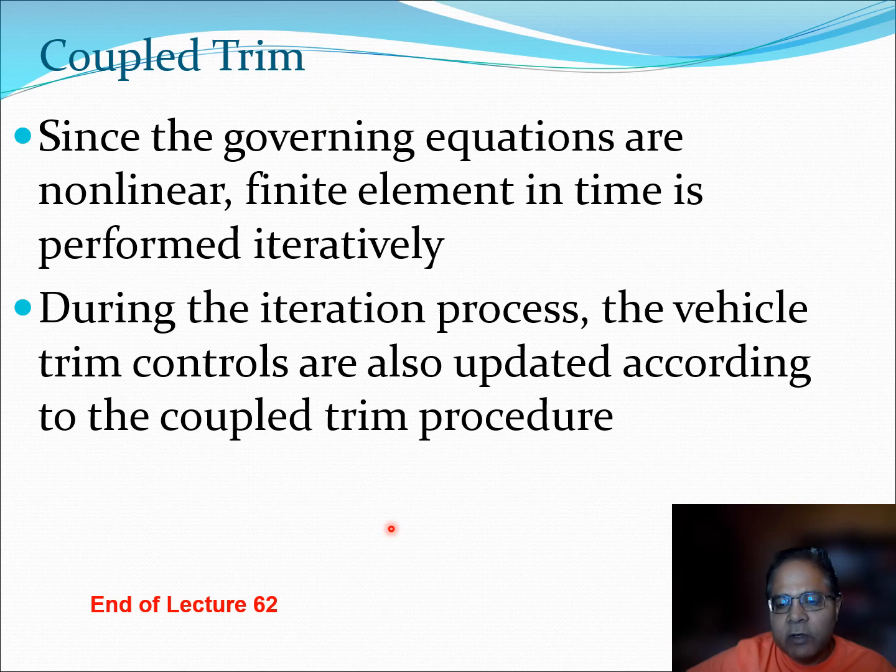So today we looked at this particular method of solving periodic differential equations. Governing equations being nonlinear, this method works out very well. You keep using this method till you converge, and during the process, if you are working on a helicopter dynamic model, you put something known as trim controls, which are essentially theta 0, theta 1c, theta 1s, and the vehicle orientation in space at that particular time.